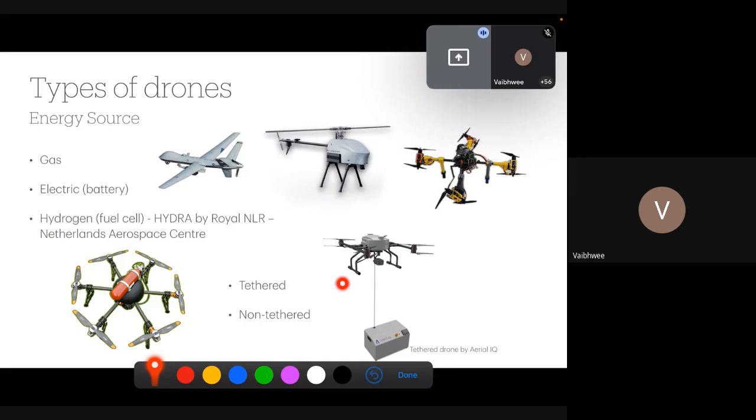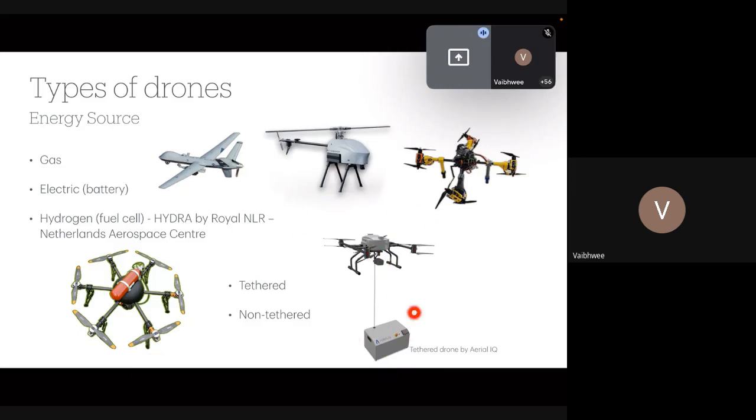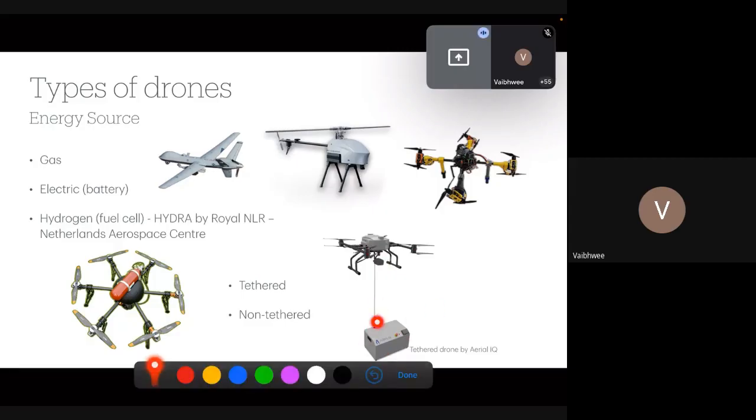So if you can see in this figure, this is a quadrotor which is tied to a tether to a ground station. The ground station supplies all the power through this tether, and the data that is to be transmitted goes from the UAV to the ground station through the tether. So there are two cables that usually run. One is the power cable and another is the data communication cable. The advantage of this is, depending on the continuous operation limit of the actuators and onboard electronics, this tethered vehicle can remain up for a very long time.